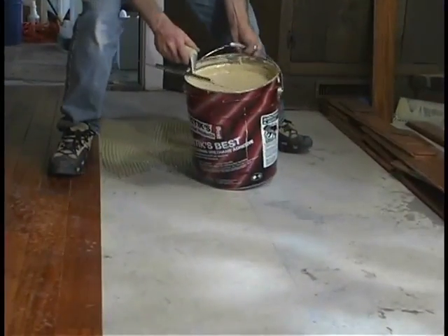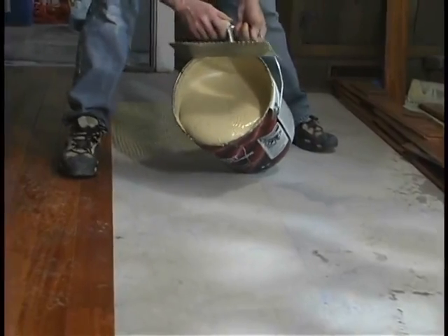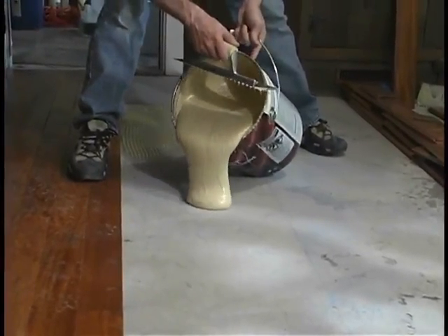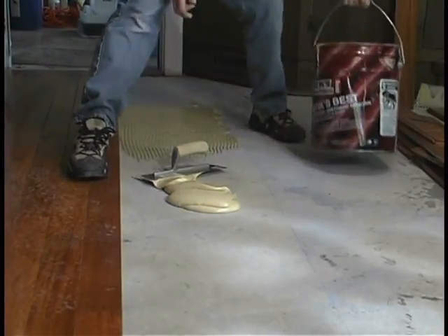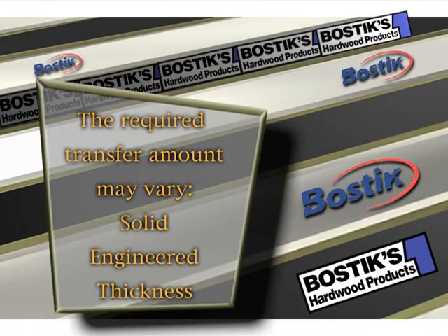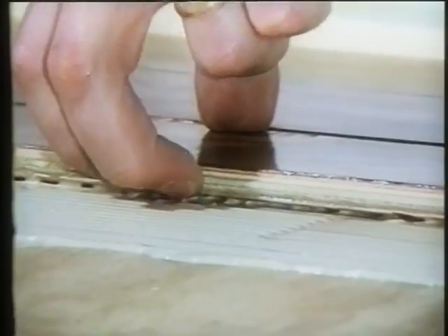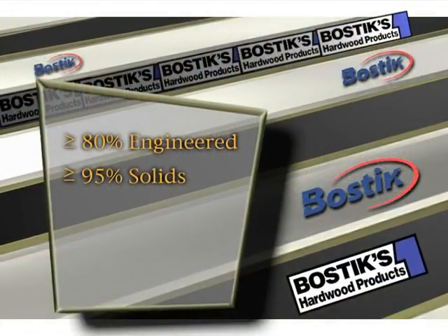Bostik adhesives apply in much the same manner as MVP4 by tipping the bucket slightly until the adhesive begins to pour. Again, you can use the flat end of the trowel to cut the adhesive and stop the flow. The amount of adhesive transfer required by Bostik may vary depending on whether you're using a solid or engineered wood flooring product and the thickness of the wood. You'll help to ensure that the right amount of adhesive is applied by occasionally lifting a board to check the amount of adhesive that is transferred to the wood. Bostik requires an 80% transfer for engineered hardwood and 95% for solids.